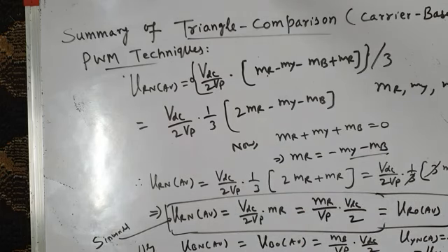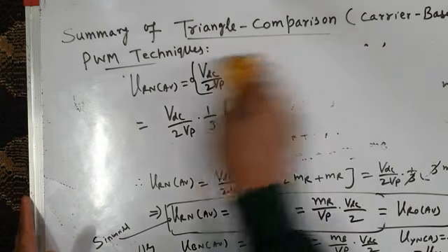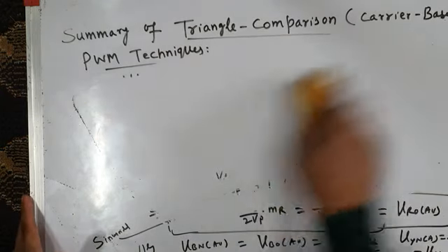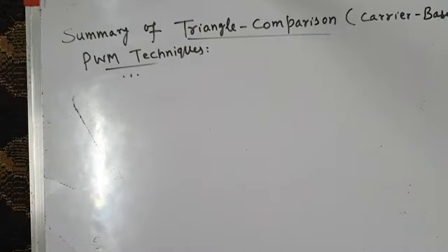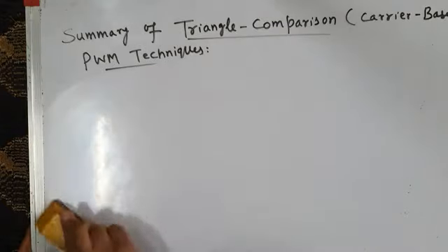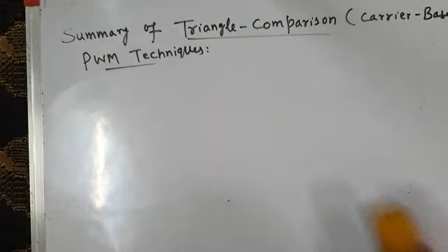In fact, the line voltages or pole voltages are scaled versions of the modulating waves. So that was about the case where modulating waves are purely sinusoidal in nature. What if modulating waves are not sinusoidal in nature? I mean, if we go for common mode injection, because in common mode injection our modulating waves or target reference waves get modified and they no longer remain sinusoidal.